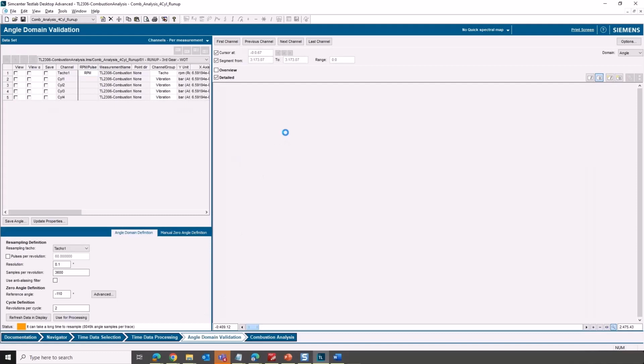So as Pete said, TDC determination is one of the critical steps. In this particular case, we would have liked to have the data for the TDC determination. We would have gone through the process of motoring or the proximity probe. For this particular data set, unfortunately, we didn't have that, but we knew that the reference angle is at negative 110 degrees. So we know that, and we can specify it here in the bottom left-hand side. I like just knowing it. It's a lot less work.